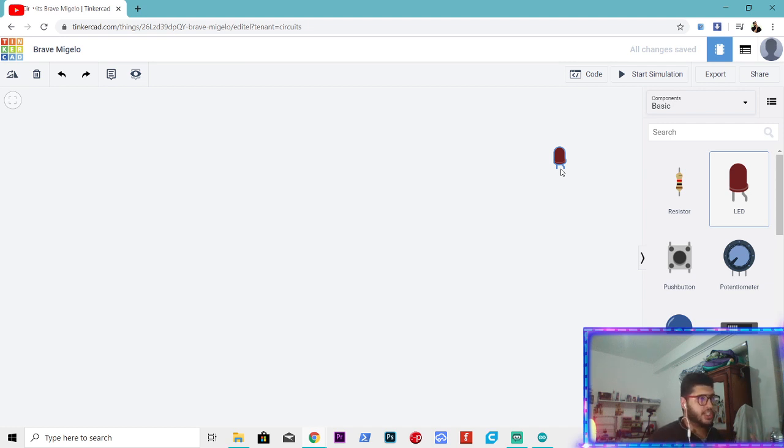Because this is a rather simple example, we can put it in any pin. But if you are working on complex robots, then you need to know which pins are free, because the same Arduino can be connected to motors, motor drivers, servo motors, LEDs, and a lot of components.